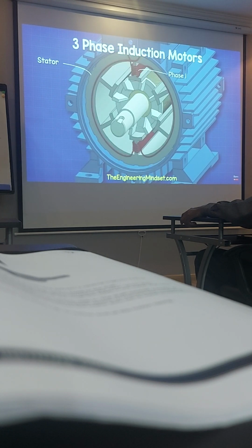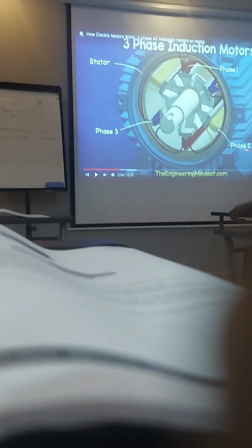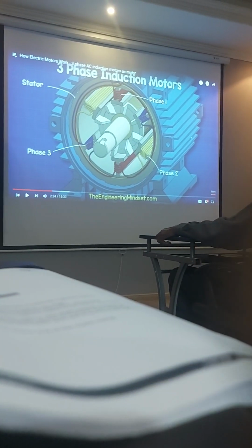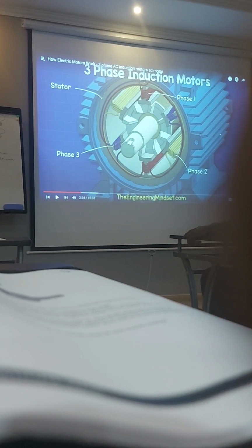Now, this is a three-phase induction motor. So, we have three separated sets of coils. So you can see here the three-phase induction motor. The stator coils are three different separate colors. You can see red color R phase 1, yellow color phase 2 and blue color. We call this RYB. So this red color you will give here one. The wire will be connected to the terminal box, and here will be connected to the terminal box. So we have primary wire and secondary wire. Primary wire will be denoted as U1, V1, W1. Secondary wire will be denoted as U2, V2, W2.